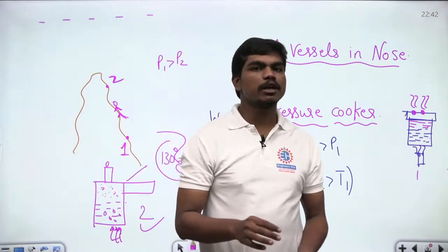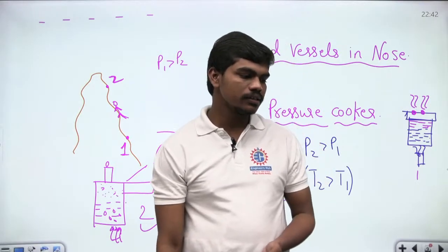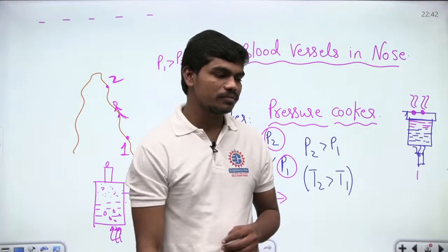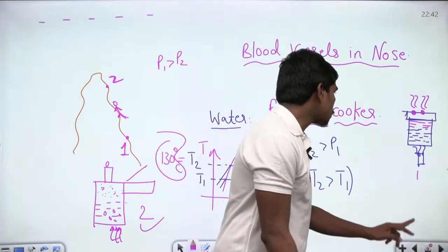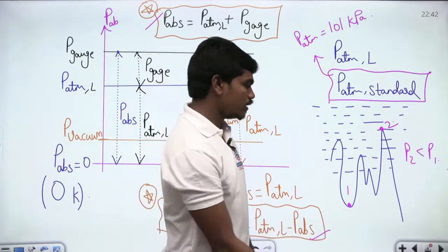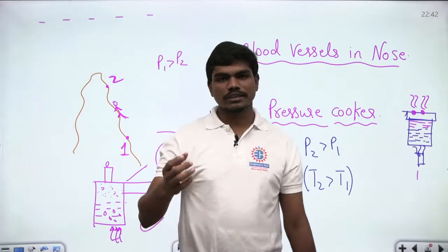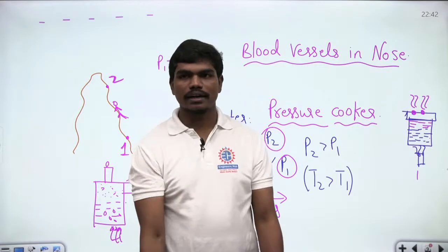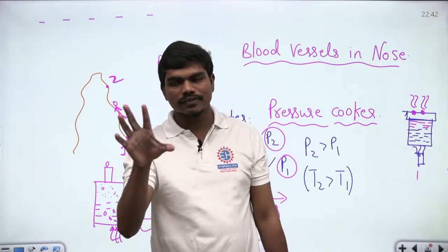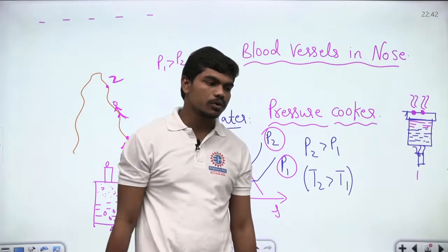How quick? You need to go into a bit of thermodynamic analysis. Okay? Clear? So all these are consequences of pressure. So you have also seen how to measure absolute pressures in case of gauge pressures and vacuum pressures as well, and all these are some applications of pressure. Okay, so we got the concept of pressure and we also saw Pascal's law, and Pascal's law tells that in a static fluid, meaning in a bulk of static fluid, at any point the pressure will be the same in all the directions at that particular point. Is that clear to all of you?